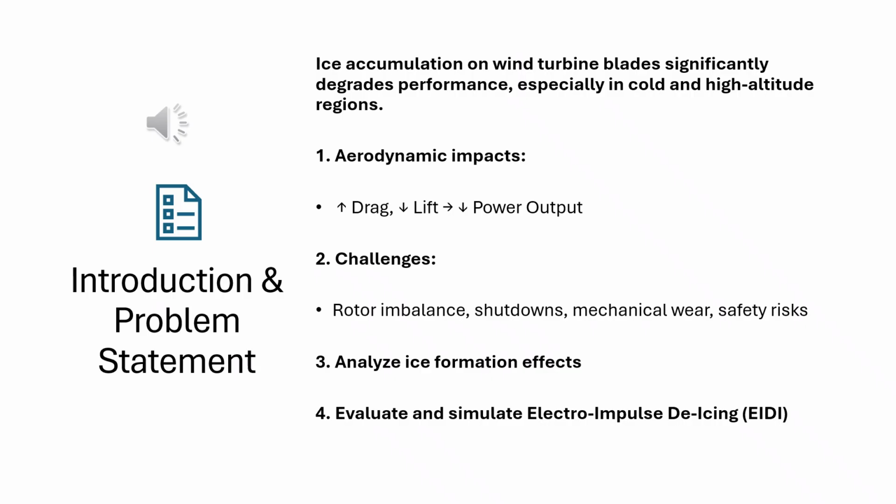vibration alarms. Our project addresses these challenges by first analyzing how ice affects turbine performance aerodynamically and operationally. Then we focus on evaluating electro-impulse de-icing, or EID, as a promising technology that removes ice using electromagnetic forces rather than traditional heating, making it more energy efficient and potentially faster. We model and simulate the EID system in COMSOL to gain insight into the physics of Lorentz force generation, magnetic field distribution, and their mechanical impact on blade-mounted ice.